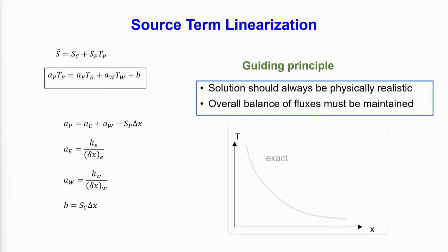You can take the source term as any arbitrary function of temperature, as with the profile assumption, but the finite volume method gives you the flexibility of taking the source term's dependence on temperature in a manner which is different from any other temperature variation that you have taken for other terms. So, you do not have to take the same approximating function for all the terms. The reason is that this is only for the integration, and once that integration is done, the history of how it was done may be lost, and that is not important.